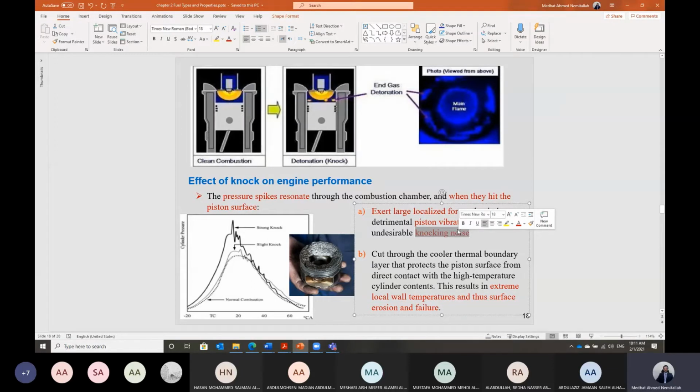We have several pressure waves due to the several combustions or self-ignitions inside the cylinder. Those pressure waves or pressure spikes hit the piston, and it creates vibration of the whole engine. As the engine vibrates you also have some noise, some knocking noise, like when you are knocking a door. It is exactly the same situation. The piston is oscillating, vibrating due to this successive pressure rise inside the cylinder, and it causes engine knock.